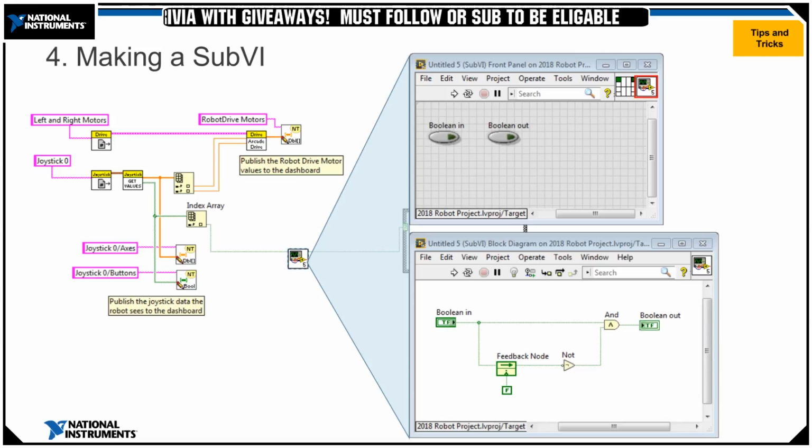I said that sub-VIs help make LabVIEW more readable. It really helps if your sub-VI icons are descriptive. If you just end up with 15 of those generic sub-VI icons numbered 1 to 15, it's going to be really, really hard to tell what your code is doing.